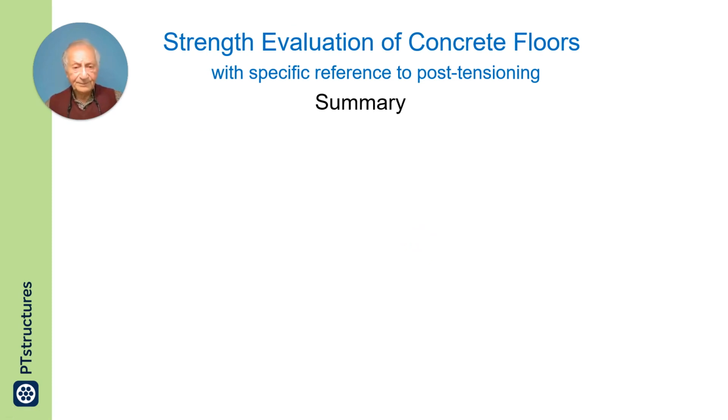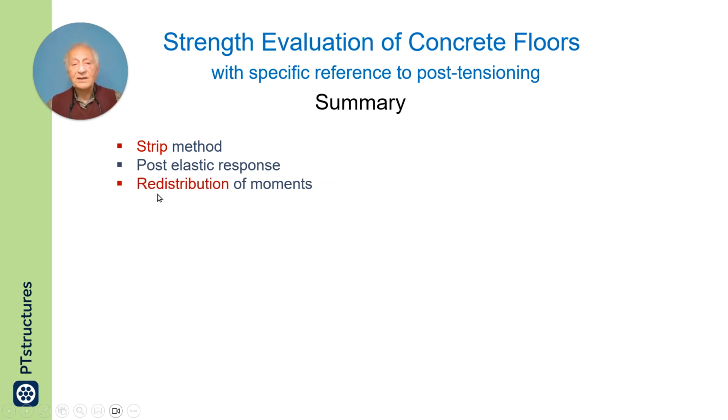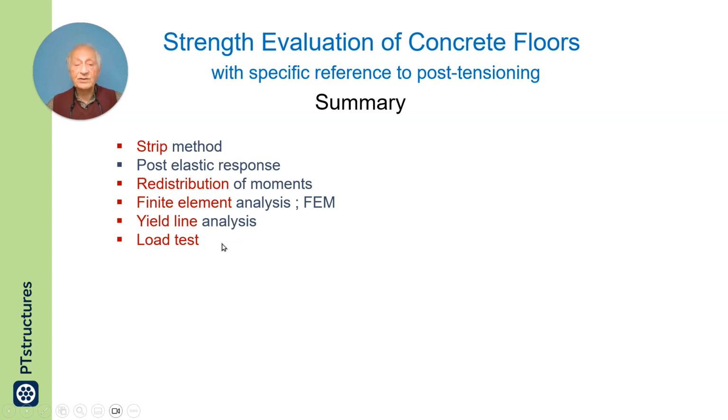So, what did we cover? Talked about strip method as being the first step in evaluation of the capacity. If it doesn't work, we go to post-elastic response. Then we used the redistribution of moments, finite elements. Then came to yield line analysis, and load test I did not cover. I just mentioned that is the ultimate if the yield line doesn't work.